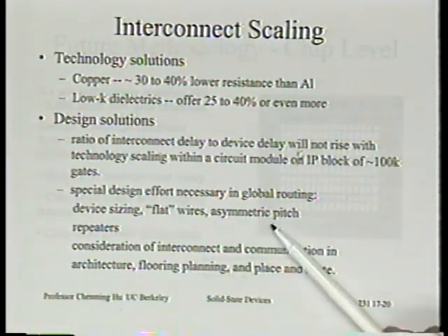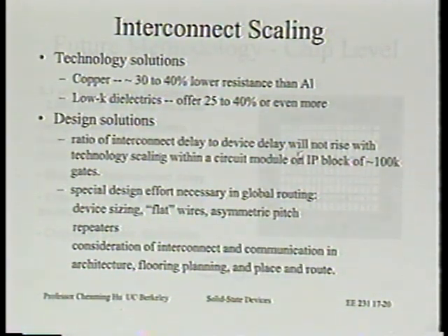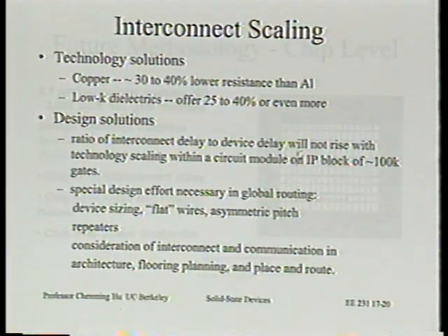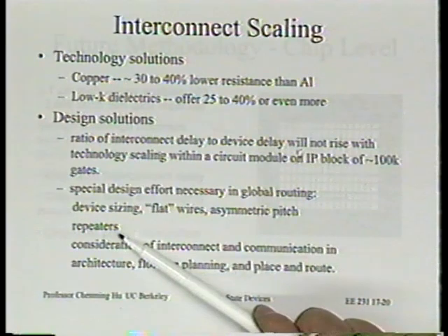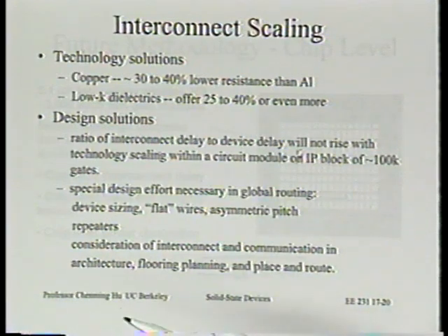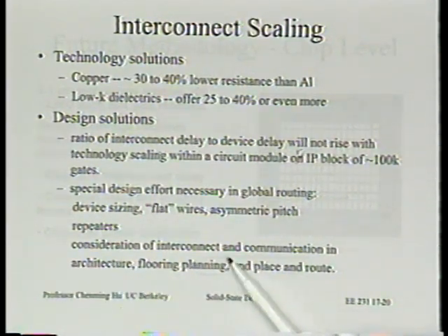Certainly the pitch should be carefully optimized. The standard design style still is that width and the gap are the same, right? And we want to see how we can optimize that. Repeaters, very important. That's breaking a wire into several steps. What's interesting is that most of the studies, including what Kevin has shown, one really doesn't want to use too many repeaters. Actually, it does not require that many. One repeater, at most two, is really good for the largest chip. So this is a little different from the view some people hold. Consideration of interconnect and communication in architecture and floorplan plays a role. That is really where the game is going to be.